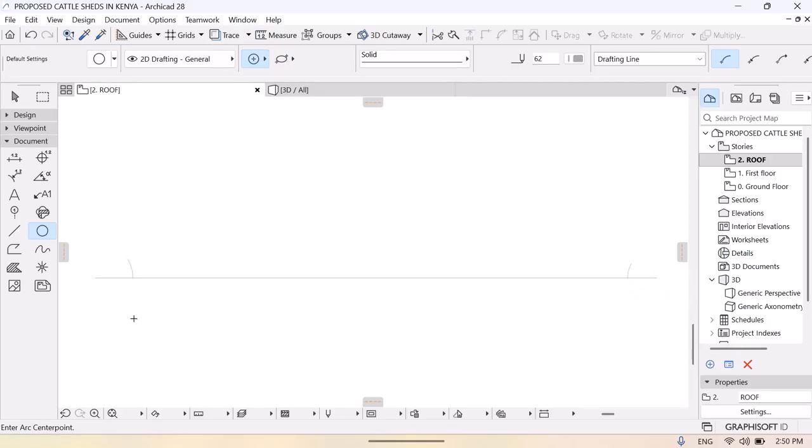which is that, and come to the line tool, join them to that. This other side, do the same thing. Remember, according to our calculations, our king post height, which should span from the center of our span, from this point to this point, should be about 5.9 meters.